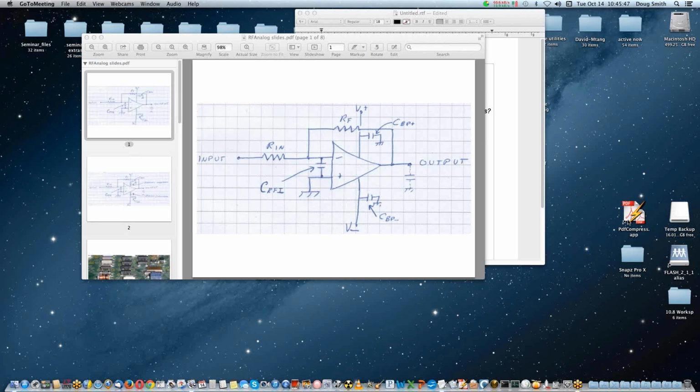Standard procedure. Yes. But if you select something other than a metal can, you cannot trust any of the published shielding effectiveness numbers because they're all far field, and we may be talking about a near field possibility. For instance, the op amp may be picking up RF from the next board over or something on the same board. All the shielding numbers published are far field, and for close field, they're way off. They don't even hold. You have to do your own tests.